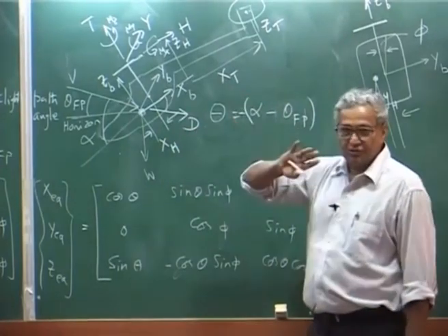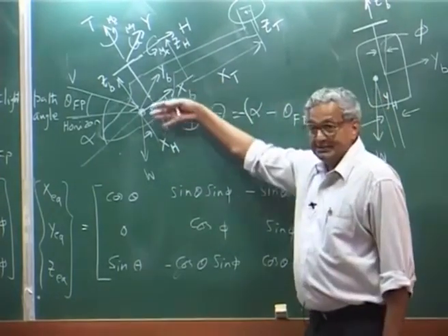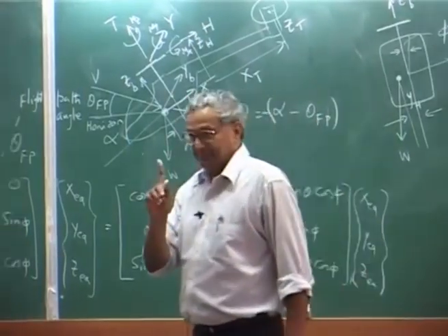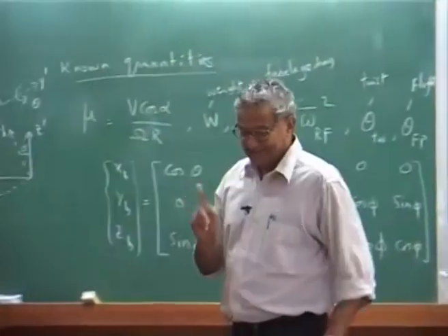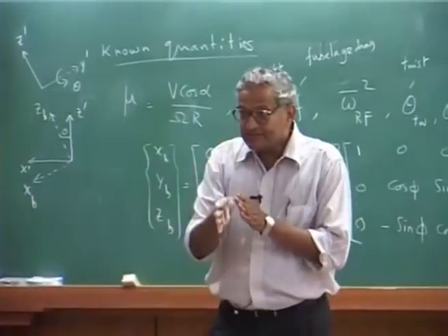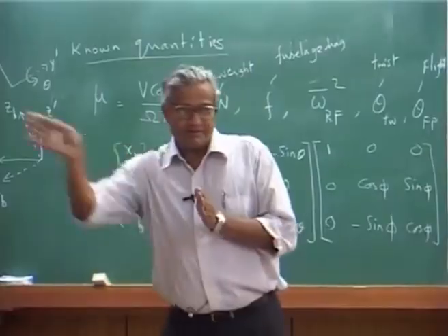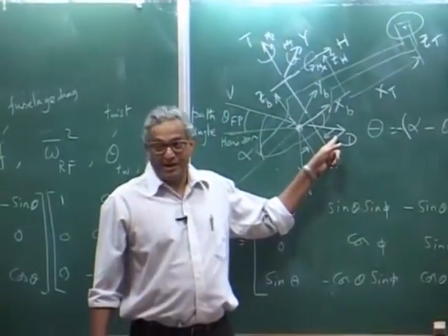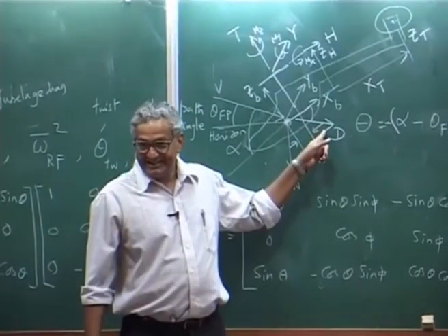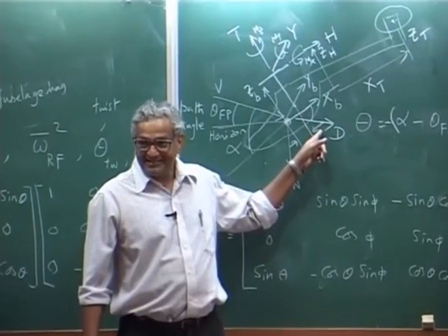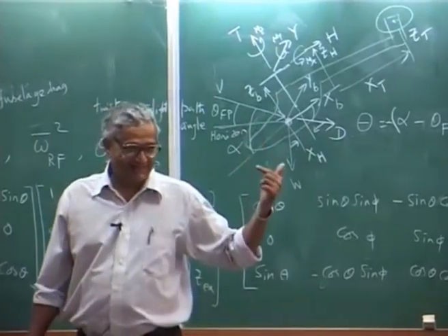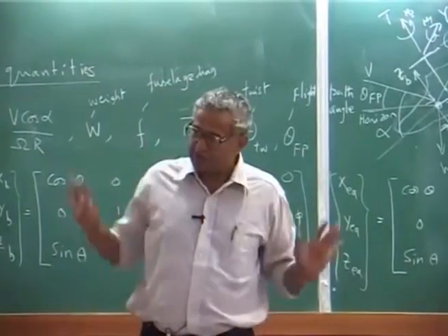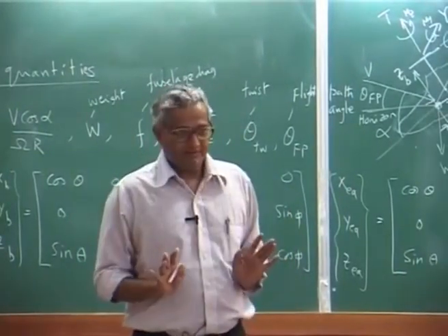And the velocity we took as though it is in the x z plane, please understand. That is why I said velocity is in the x z plane. Suppose the velocity has a side component, the drag will not be in the x z plane, drag also will give a side force, you follow. So, when you do it vectorially, you have to do everything properly.